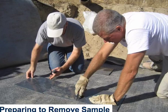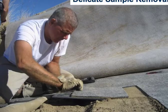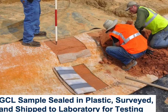Here you can see Dr. Benson cutting out samples. And then we'll take those samples and we'll carefully transfer them to the sampling plate. And so delicate sample removal here. You can see the concentration on Dr. Benson's face as he's carefully trying to remove this without deflecting the sample, without disturbing the sample to the greatest extent possible. We'll then take that sample, we'll wrap it in plastic, typically load it in a box full of soil to provide a little bit of overburden and also protect the sample during transport back to the lab. And we'll survey the location of the sample prior to leaving.